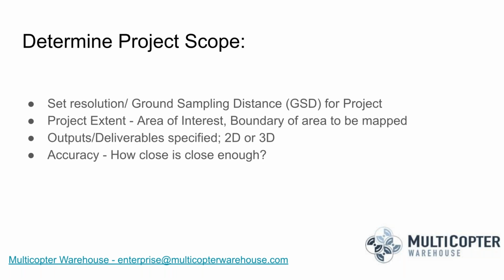Yes, sir. Well, the Pix4D capture application can work offline, but the one caveat is that you wouldn't get the background maps or the background data to help you lay out where your project's going to be. But if you plan your project back in the office, you can essentially cache that information or download it, so you can then go out and use the Pix4D capture, have your background imagery, and be disconnected.